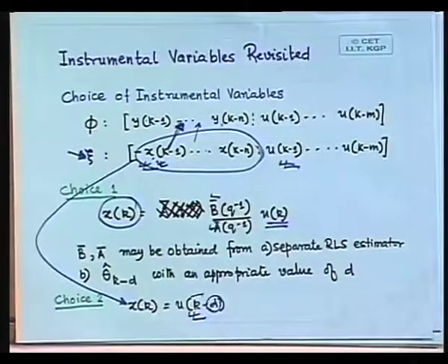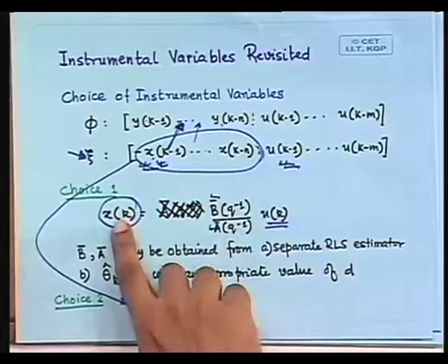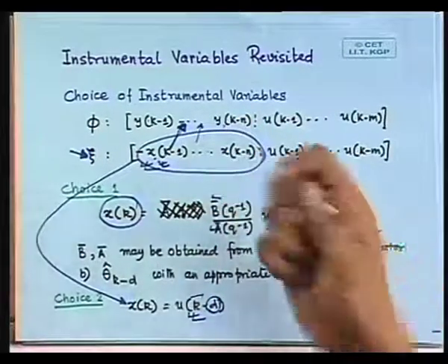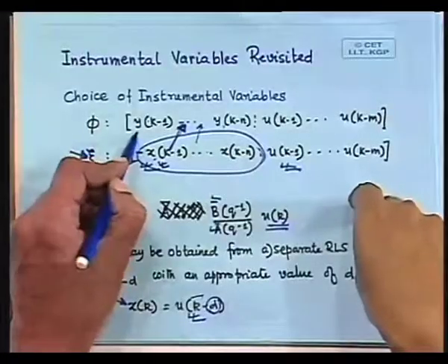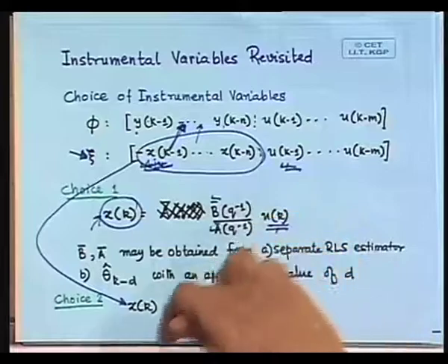Fact number 1 is established. And the second is that even though these parameters are slightly erroneous, this x is going to be highly correlated with y, obviously. There may be a little bit of error, but after all, the least square algorithm works. So another approach is to use some approximate least square, go on simulating x using the same u, and then use this x here. It can give you a significantly better parameter estimate when you have correlated noise. This algorithm really works well.